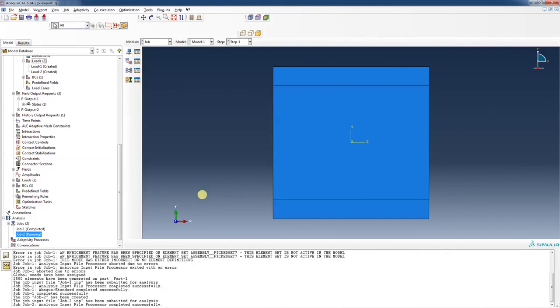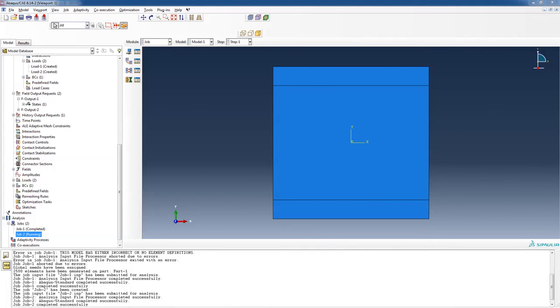We'll let it run here for a moment. As I said, take a look through the theory manual and read about the extended finite element method. Some of the limitations, some of the capabilities of it are explained in the manual. And I noticed there's a lot of other good examples on YouTube of using XFEM in three-dimensional type elements. My initial goal was to try to have a CAD geometry, bring in an arbitrary CAD geometry, partition it, mesh it, and then use XFEM on it. But I've had trouble finding the right kind of mesh to bring in and apply to this method.